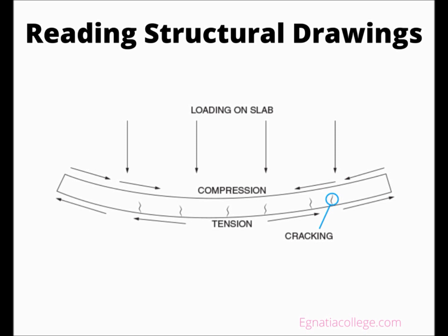Schedules use different shapes, such as a triangle or hexagon, to denote a reference to different schedules, just as in architectural drawings. The reference to details is the same as in the architectural drawings: a circle with the detail sheet number on the bottom and the detail number on the top. Foundation.